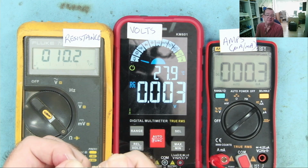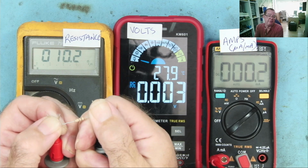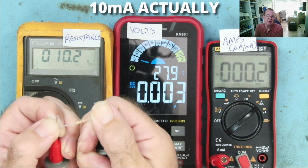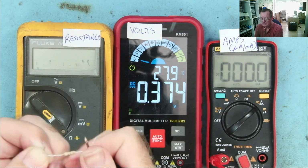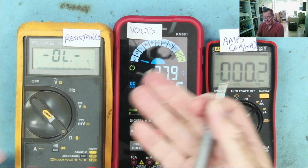We're now reading 10 ohms, okay, and you'll see the voltage has gone down to 0.003. So you can see that at very low resistances, this meter can no longer provide the constant voltage of 0.1. That's because at 0.1 volts through a 10 ohm resistor, it would have to pass about 100 milliamps, and it's not able to do that. So apart from very low resistances, this is a constant voltage generator. You'll also notice now that the voltage 0.003 is about the same as the current 0.3 milliamps. So that's how it's working.